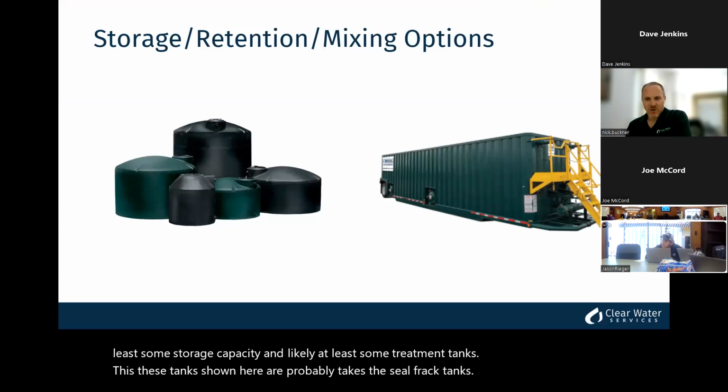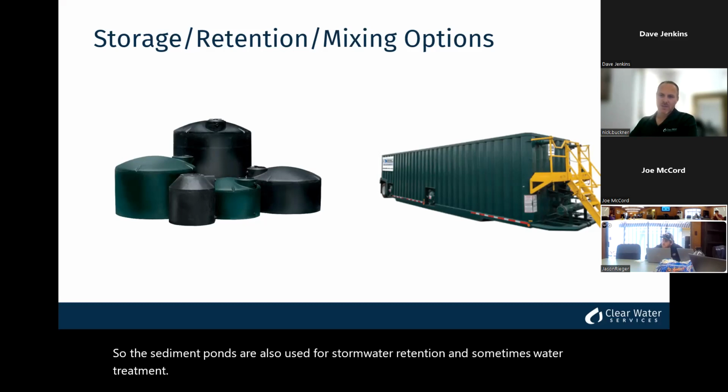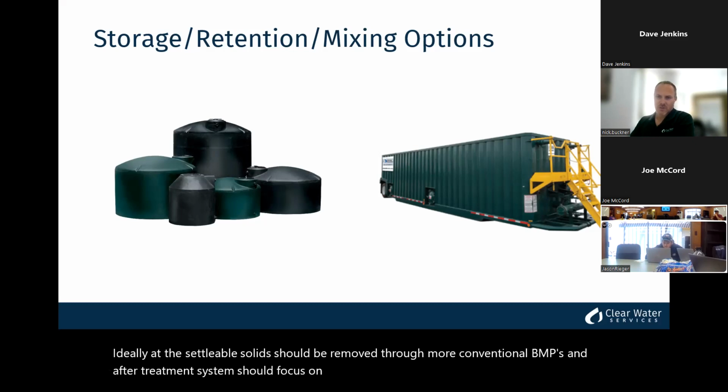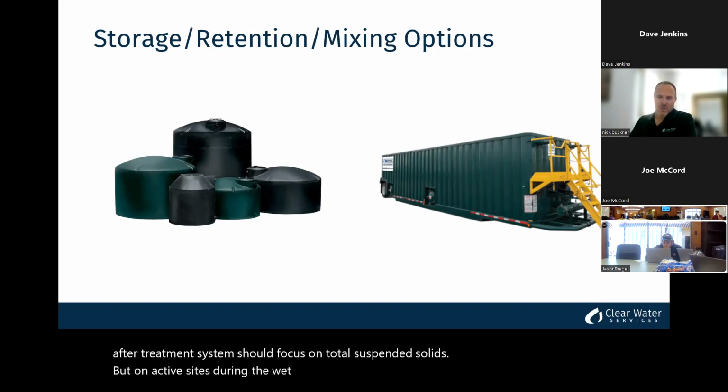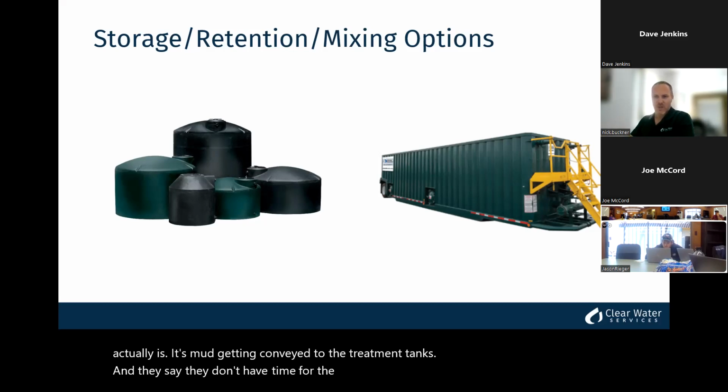So the sediment ponds are also used for stormwater retention and sometimes water treatment. Ideally, the settable solids should be removed through more conventional BMPs, and an active treatment system should focus on total suspended solids. But on active sites during the wet season, we see water that should just be called what it actually is. It's mud getting conveyed to the treatment tanks. And they say they don't have time for the mud to settle, they've got work to do. So you guys deal with this.